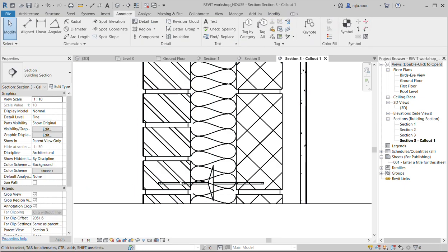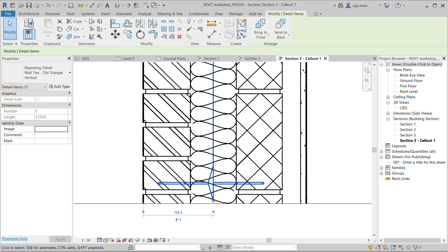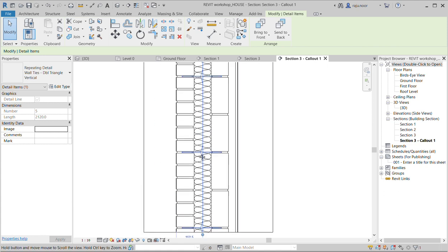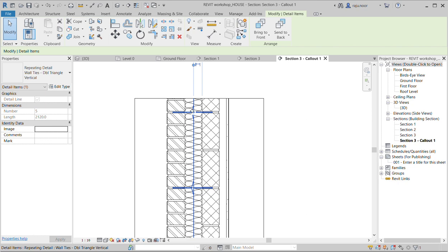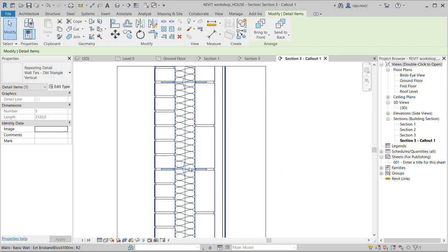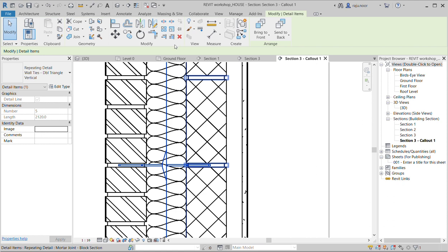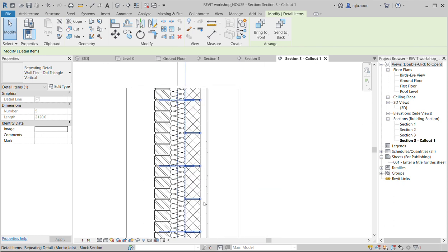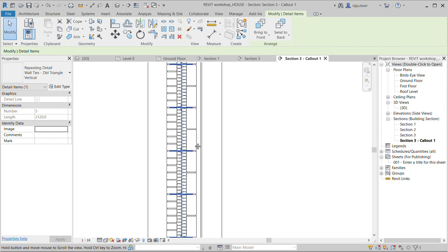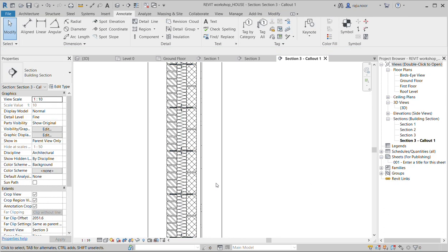So if you find it, use your arrow buttons on your keyboard to put that into position, so that you should see that they line up on either side, and it's in the middle. And then it goes all the way. So if you've done the mortars right in one instance, this should all be right after that, because it's all pre-programmed in terms of the right distances, right centers. Okay, so every 2 blocks there typically is a cavity mortar, a cavity wall tie.